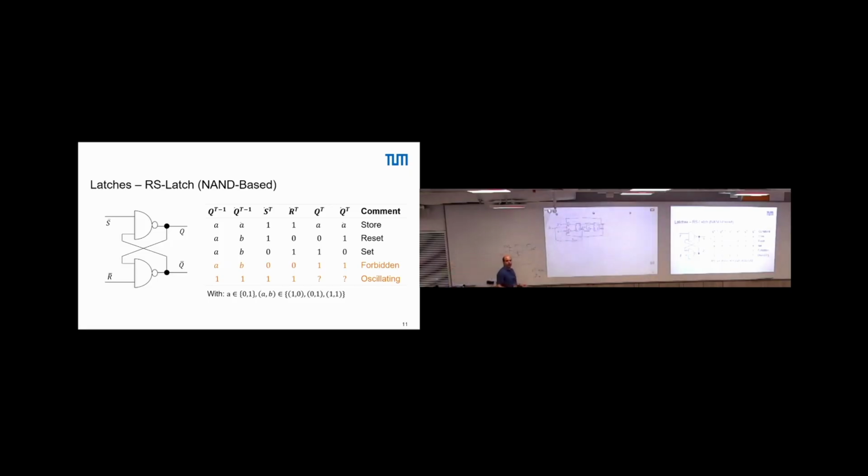And then we had some hold time problems. That the signal should be stable after a clock edge. So what does this relate to? Well, effectively, we have some feedback that must be triggered, right? And only when the propagation back here is completed, only then we can be sure that any signal that comes in does not unintentionally modify what we have here. Yeah? So we have effectively some feedback loop, and that corresponds to our hold time.